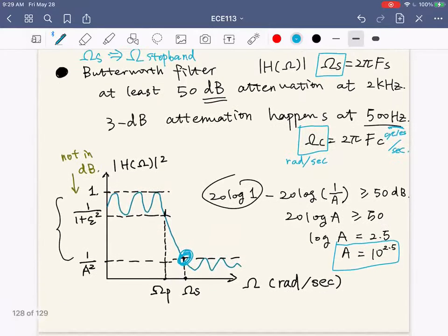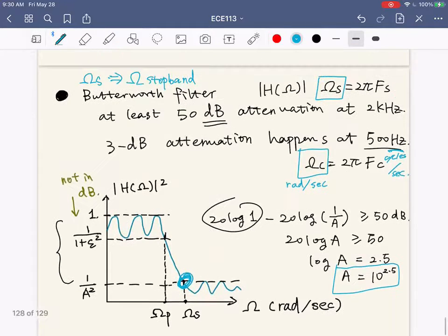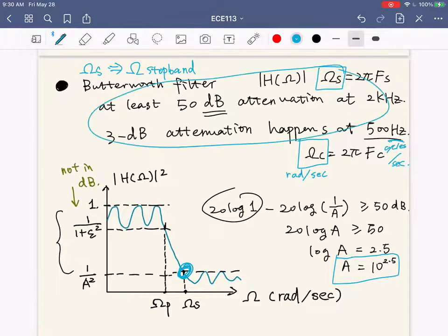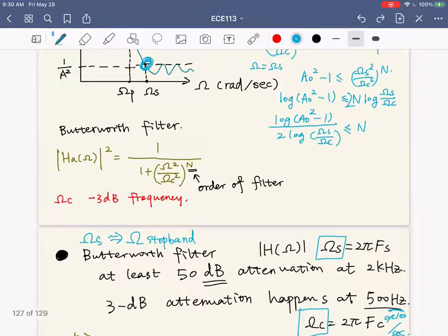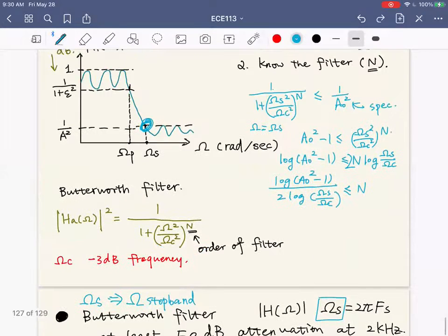Quick question. How did you know this is the IIR filter? Is it just because Butterworth is always IIR? You can turn this textual description into a concrete Butterworth filter, and other kinds of filter will have different expressions of their square response. Then you just derive it using this method. Take log at both sides and be careful about the direction of the inequality. Or, in the other way, you can directly use the formulas they give to calculate your n.